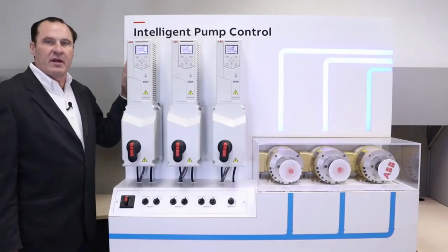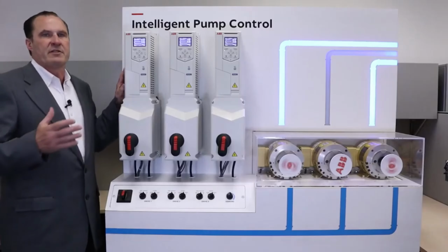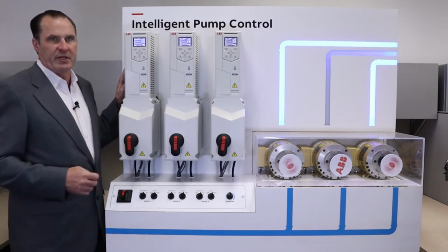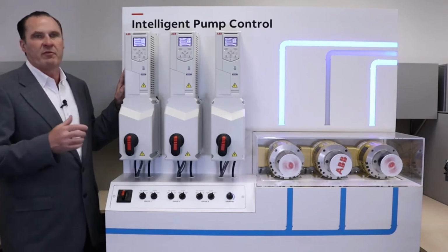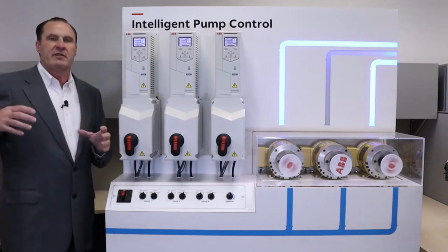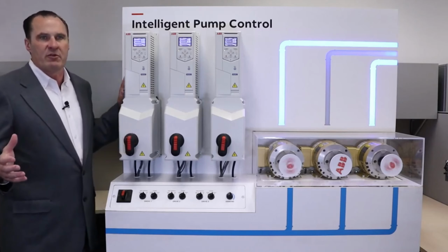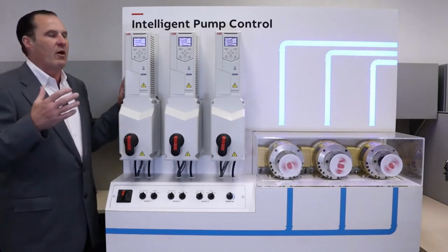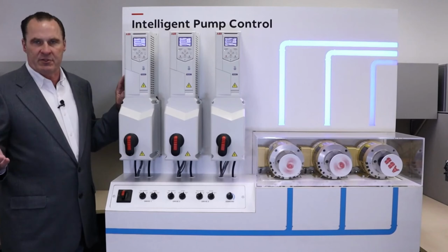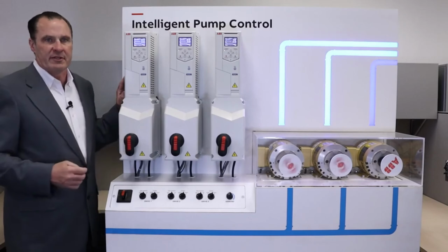Now let's take a look at the individual drives and look at actual programming of the parameters into the drives. Programming the ACH580 Intelligent Pump Control System is simplified through the use of an inverter-to-inverter communication link. This link allows for automatic parameter synchronization between the drives. Program each individual drive for its connected individual pump and motor characteristics, then program one drive for the intelligent pump control features that you want. That drive will automatically update the other drives in the system. Any drive can be programmed to be a master drive. The master drive controls the other drives through the inverter-to-inverter communication link.